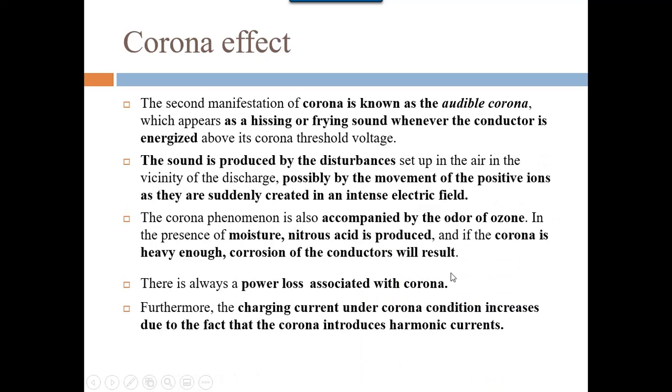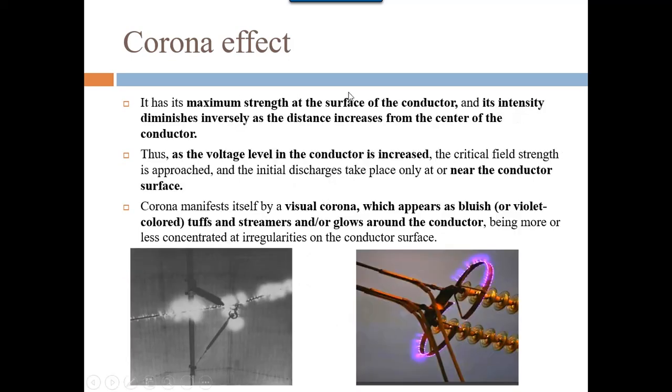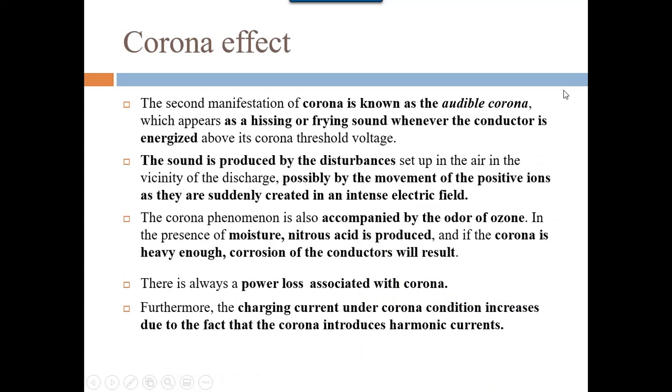The second possibility to check when corona occurs is audible corona. The first one is visible corona, visual corona. The second one is audible corona, which appears as a hissing or frying sound whenever the conductor is energized above its corona threshold voltage. The sound is produced by disturbance set up in the air in the vicinity of the discharge, possibly by the movement of the positive ions as they are suddenly created in the intense electric field. The corona phenomenon is also accompanied by the odor of ozone.